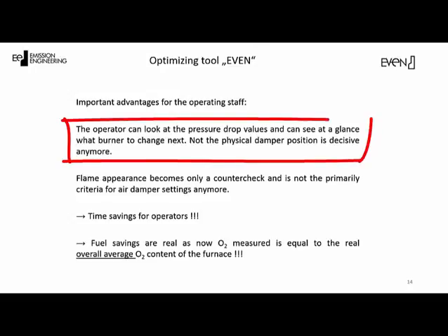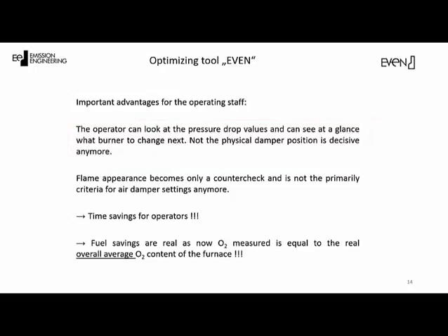Now you can see that one glance is enough to perceive which burner has received more or less air, and with just a few quick damper setting changes, an even distribution is achieved. This allows field operators to focus on other critical equipment.